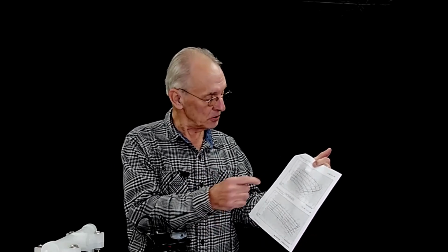Okay? And when you talk about centrifugal pumps, you talk about them operating on the curve. And somebody will say, it's operating off its curve. They can't. They are always on the curve. They're just not on the curve where you want them. In other words, for any given flow rate and any given pressure, the line shows you what you're going to get at 1,750 RPM for this pump.